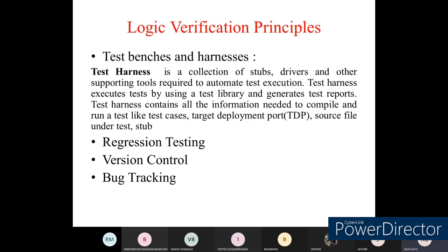The next one we call the system level. In the case of the system level, we have done all the fabrications and all the setup has been initiated once the design of the chip has been done. When we want to check the functionalities of any application or any working principle, then we need to check the entire system. That verification level we call the system level. And the last one is the field level. You have designed the chip and it has been tested properly in the manufacturing field. When it goes to the field level, it is where exactly it has to work.